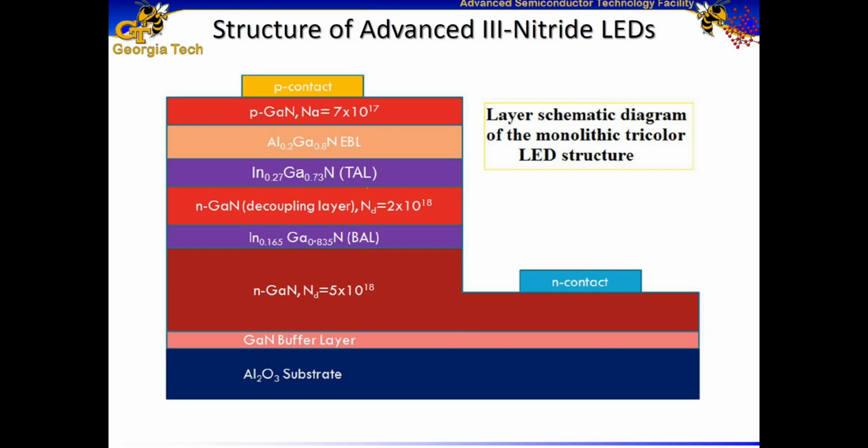And simplifying it, it reduces to our wavelength of emission is equal to 1240 nanometers divided by the band gap of the semiconductor. For gallium nitride, the band gap is 3.4 electron volts. So its corresponding wavelength becomes 365 nanometers, which is in the ultraviolet range. However, for the visible light range, our wavelengths of interest are in the range of 400 nanometers for bluish kind of light, and 750 nanometers for red light. And in between we have green, yellow, orange light as well.